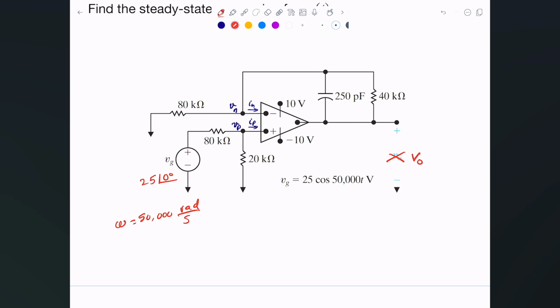And the thing that does change is this capacitor. The reason is that, if you remember, capacitors exhibit an impedance of 1 over j omega c. If we compute this value for this particular capacitor, we end up with negative 80 j kilo ohms, because it's negative 80,000 j ohms. So basically I just took the 1,000 and put it as k. And as a quick reminder, picofarads is equal to 10 to the negative 12 farads. This is very small. Anyway, you compute this, and this is what we have.